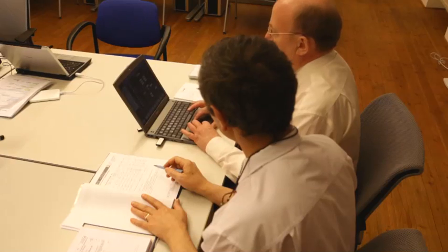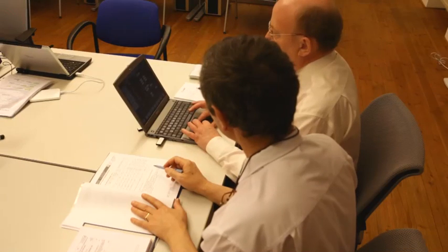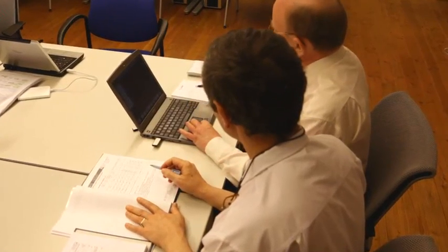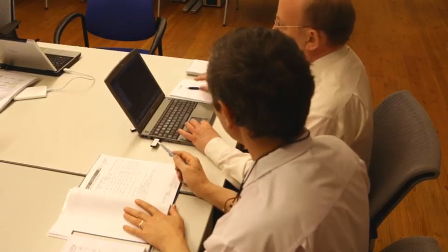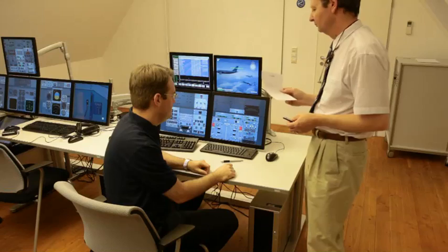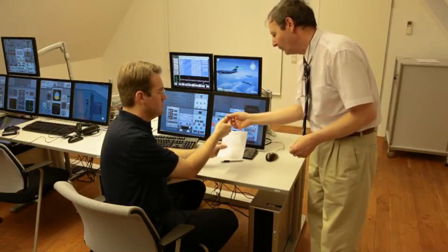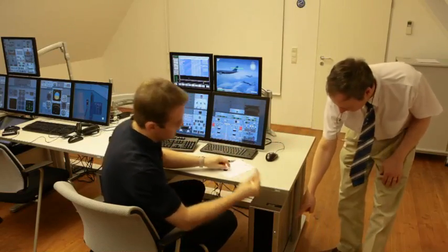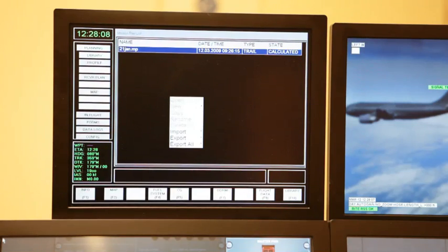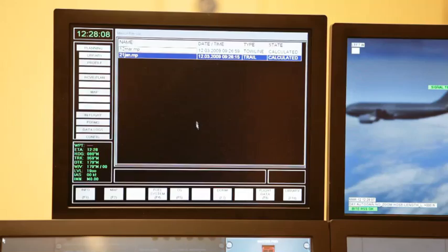An AAR training exercise starts as in reality with the mission planning. The system supports anchor missions as well as trail deployment missions. Planning comprises route definition, vertical profile, tanker and receiver fuel plans, refueling brackets, and diversion airports. Finally, the mission plan is loaded into the airborne mission computer software. The data is imported into the trainer's embedded MCS application in the same way as in the airborne system.